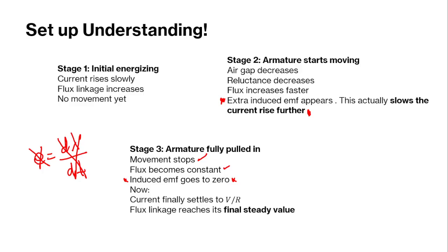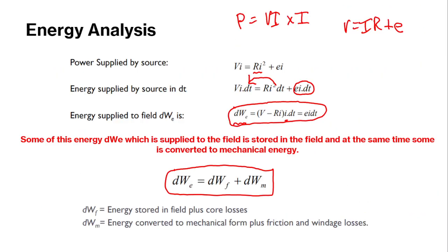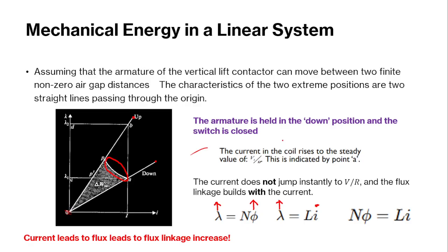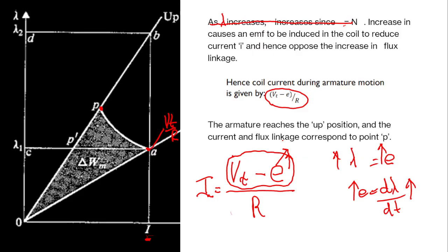Because think about it, where I drew that. Right, so these lines here, when they reach the top, there is basically one core material, and all the flux lines are cutting the material. So you're going to have a maximum amount of flux linkage when it reaches the top. There is no space to prevent it. Everything is cutting. That is at the top of the contactor. There was I here. So at the top it stops, and you have your maximum amount of flux linkage, that's your maximum value.